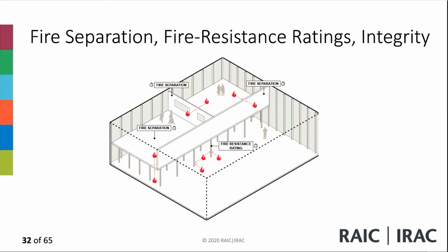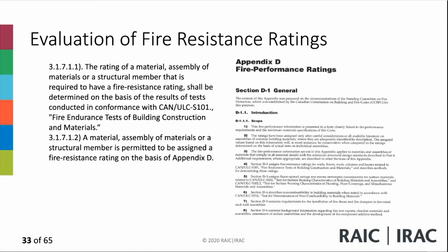So we talked about fire resistive separation and fire resistance. We know that we've got floor ratings, we've got structural ratings from Articles 3.2, and then we've got the horizontal compartmentation requirements. It comes from either the occupancy or occupancy separations. It could be from special hazardous areas and special occupancy requirements, sensitive occupancy requirements. So all that is in the fire separation. We went through the Appendix D.